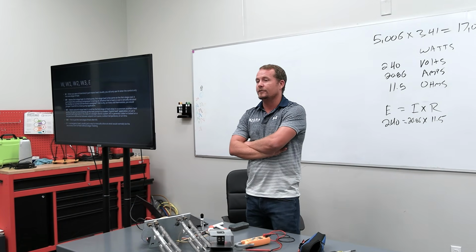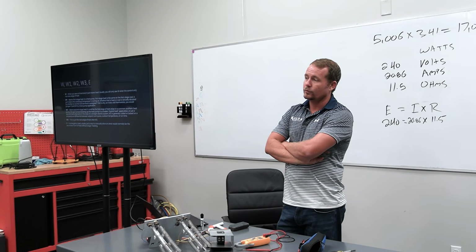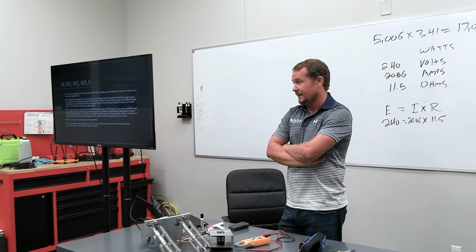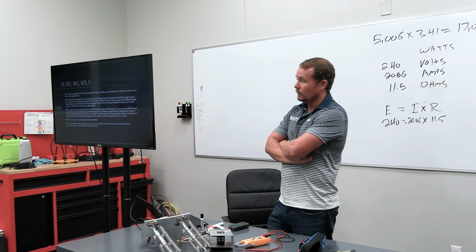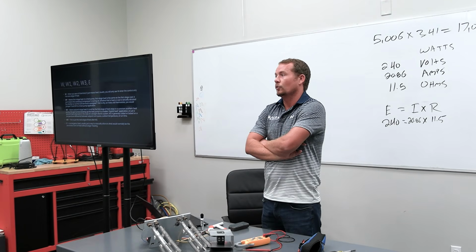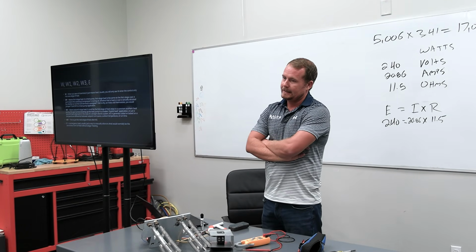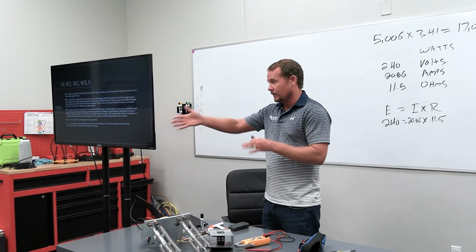That's why when 2-stage compressors first came out, we had to use 2-stage cool, 3-stage heat thermostats. That was a really big deal to find them that were that way. There weren't a lot of them made. The old Honeywell Chronotherm back in the day was one of the first kind of fancy thermostats, and you had to get the one that had the 3 stages of heat in it. Because first stage is first stage compression, you get what I'm saying.